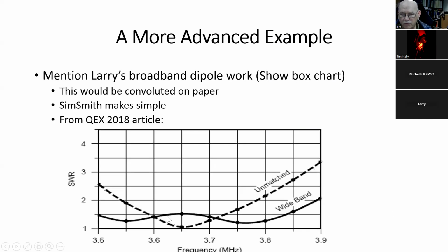Okay, so this is back to what we just saw. Now, this chart is not from the Smith chart software. This chart is what the guy measured as he did what I talked about with the Smith chart software. In the real world, there are going to be some differences. But the bottom line here is across most of the 75-meter band, SWR is less than 1.5. I think we can all live with that. And at the very high end, it's only 2.0. And I suspect your manual tuner or the tuner in the radio can live with that.